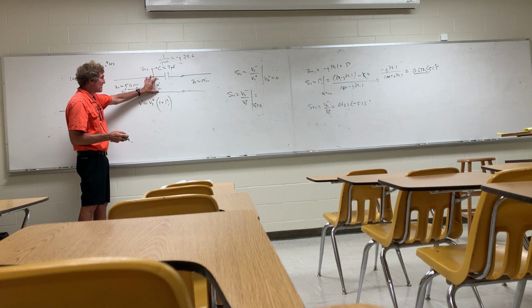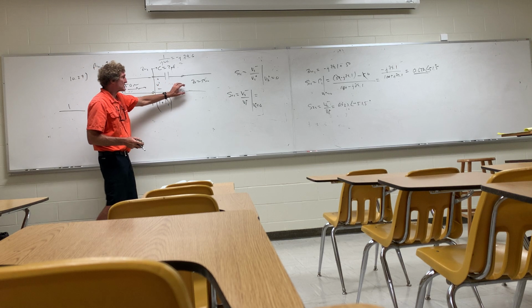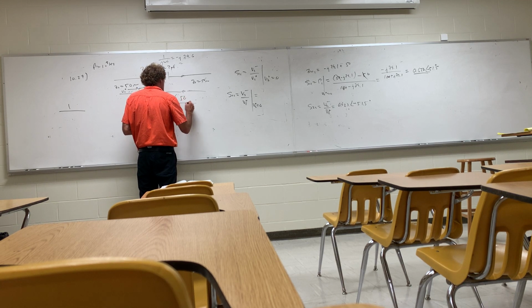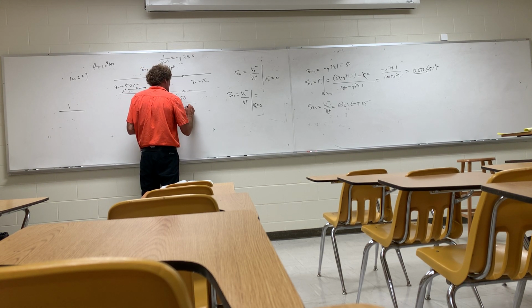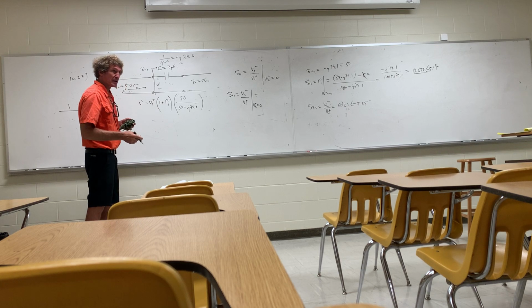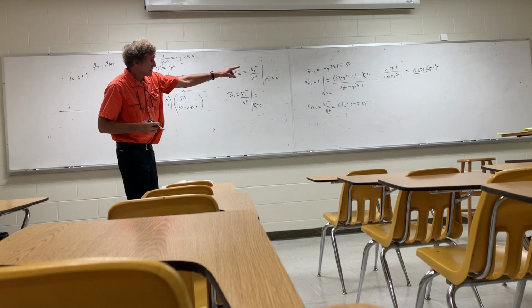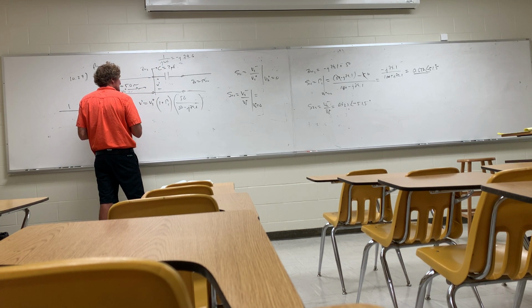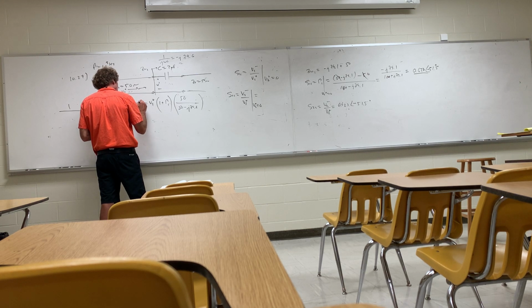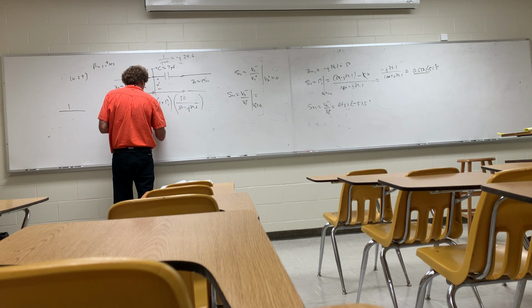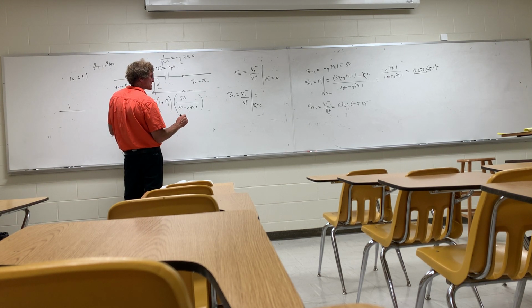Then, once I'm here and I have this, now I need to find how much of that voltage is actually developed across that 50 ohms. And that would be 50 over 50 minus j79.6, correct? Now here I need your help with calculators. That's the value that goes here for the reflection coefficient. So now I can say V2 minus over V1 plus, or S21, will be equal to 1 plus the reflection coefficient, 1 plus 0.623.